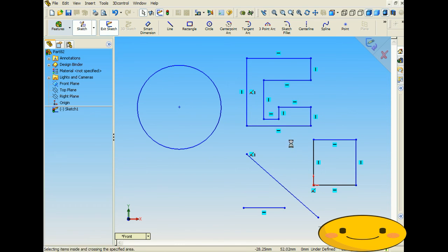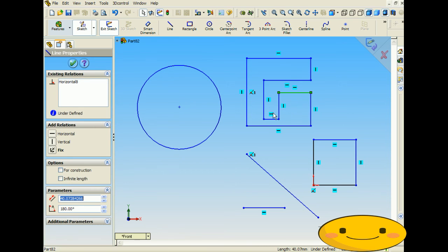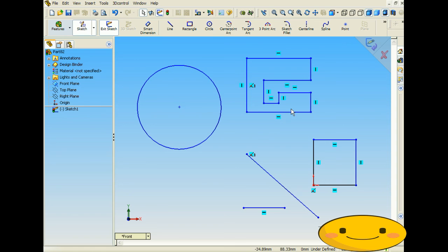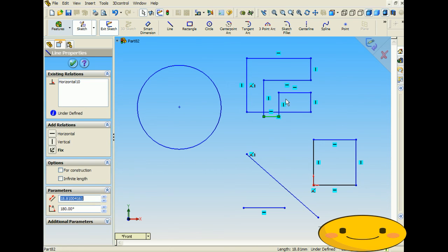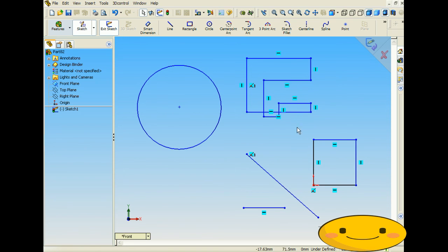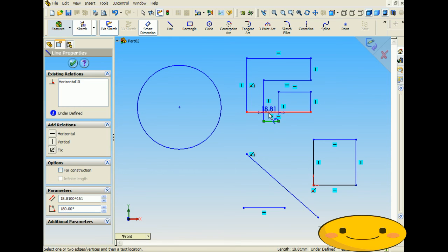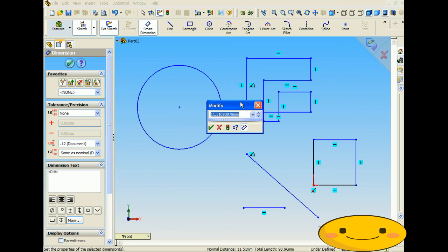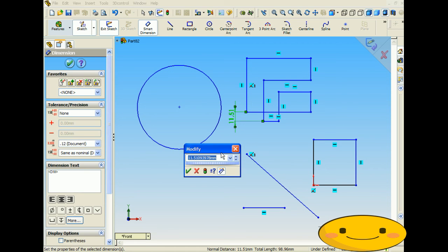Instead of putting in the dimension there, I'd actually just raise all this up and then put the dimension in to move that line up. But if I didn't do that and I put the dimension in and say everything was like this, there's no possible way to dimension these lines to go back on top of here. Because when I'm putting a dimension in here, I'll just show you, between here and here, there's no way to flip this line onto that side.